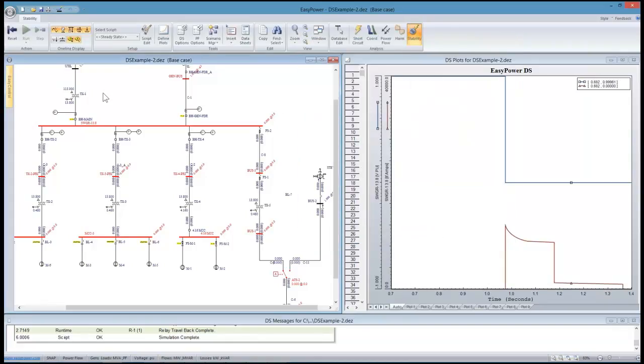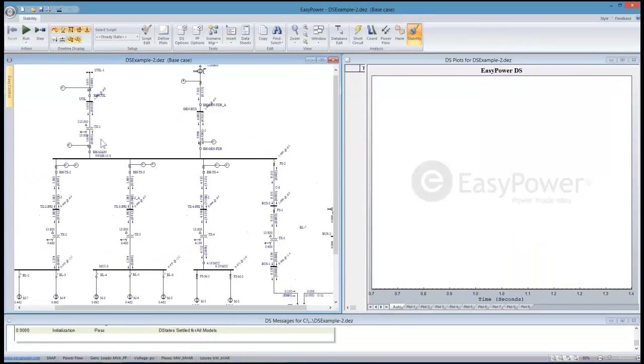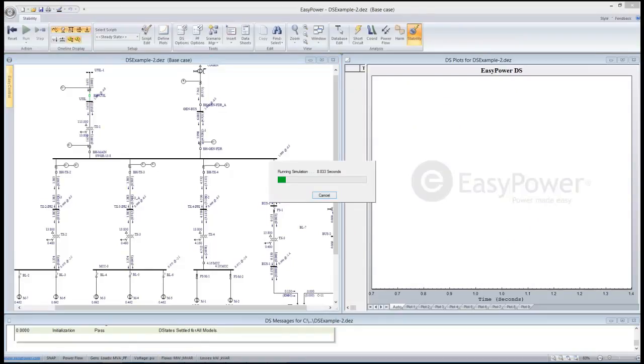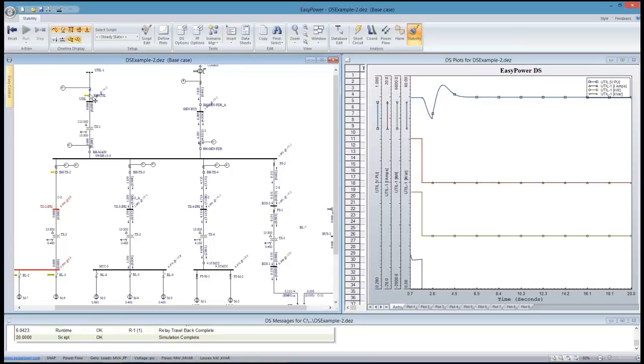Then once we've done a simulation, before we do the next, we want to reset, and as simple as it can be in the case of the utility fault, which might be to pull this particular breaker, by default, because we're on a branch, it's going to plot the voltage, the current, and then the kilowatts and the kVA, which is not all that exciting if this is the only place we're going to be monitoring.